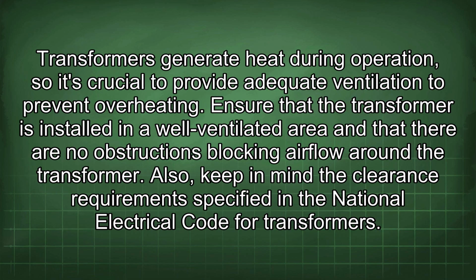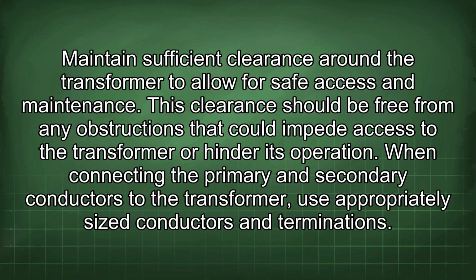Transformers generate heat during operation, so it's crucial to provide adequate ventilation to prevent overheating. Ensure that the transformer is installed in a well-ventilated area and that there are no obstructions blocking airflow around the transformer. Also, keep in mind the clearance requirements specified in the National Electrical Code for transformers. Maintain sufficient clearance around the transformer to allow for safe access and maintenance. This clearance should be free from any obstructions that could impede access to the transformer or hinder its operation.